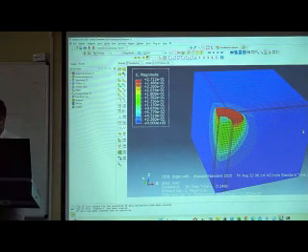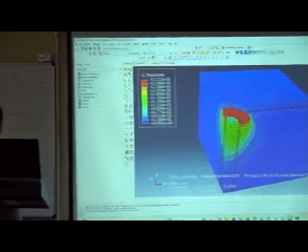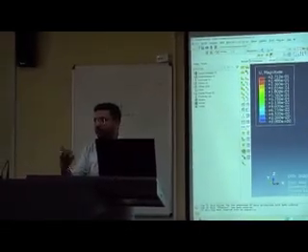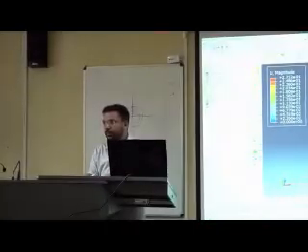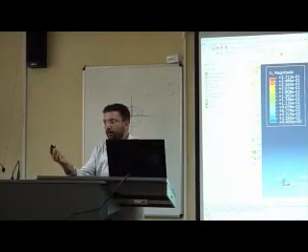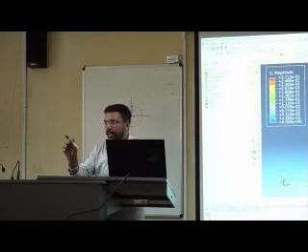Sir, the reaction force is there now. It will be in kN, so you have to divide it by the area. At every node there is a different reaction force, then you have to sum up all the reaction forces, as U is the same at every point.